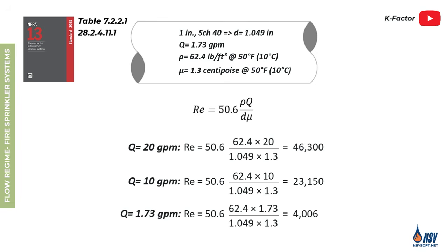In real installations, sprinklers operate at flows that produce Reynolds numbers far above the zone where flow behavior begins to shift away from turbulence. So the conclusion is straightforward. The flow of water, without any additives, in fire sprinkler systems is always turbulent. This is why hydraulic calculations using the Darcy-Weisbach equation rely on friction factor values associated with turbulent flow.